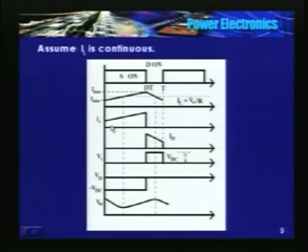So, when the switch is on, voltage across the switch is 0, and when the diode is conducting, voltage across the switch is VDC itself. I explained to you, it is VDC itself. In the period when the switch is on, voltage across the diode is the supply voltage itself in the opposite sense, or source voltage VDC.